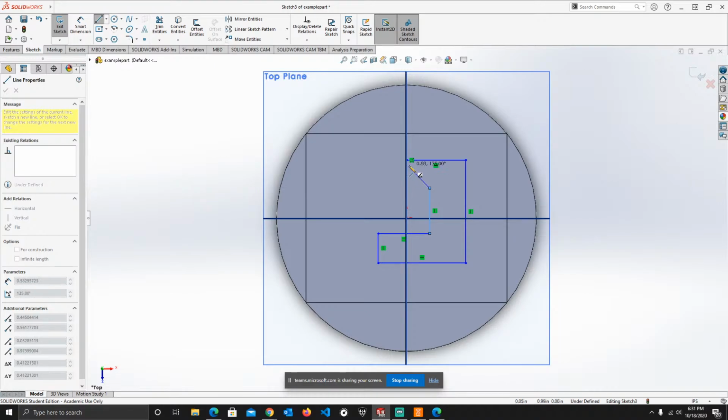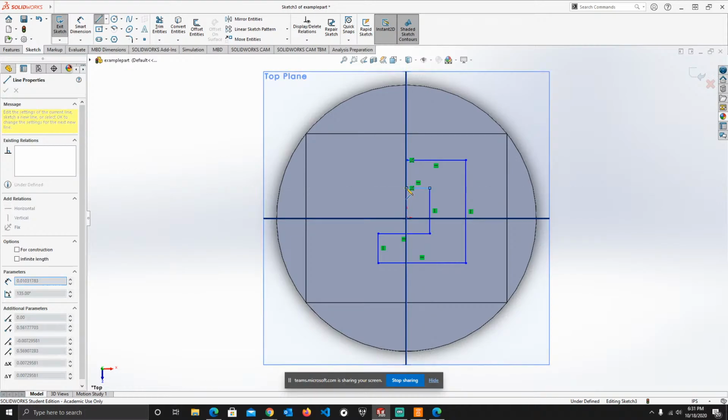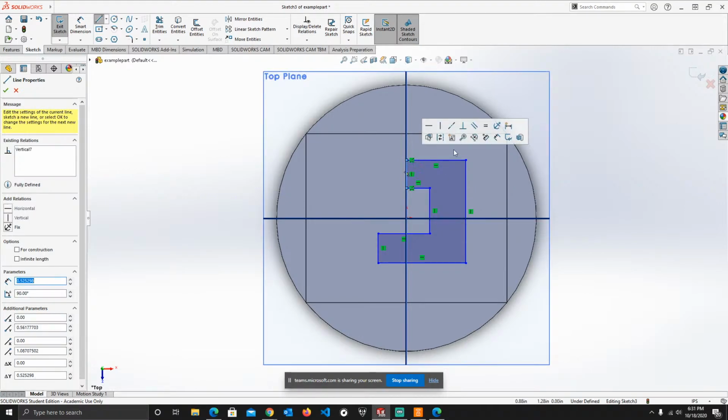Now, let's say I want to make sure that I perfectly fit here when I'm gonna make my last line. So I can always reach up to my endpoint. You're gonna see now that it changes to a yellow square with circles in it. You come down, try not to move too much, and now it changes to a horizontal coincidental. So that means that you're gonna be touching this line. Click there, and then click on your final point. And just like that, you finish your figure.